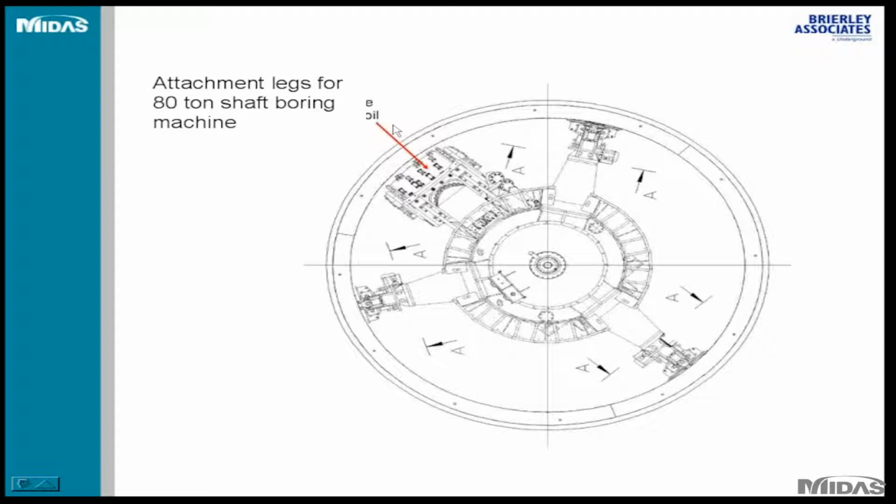You don't need them. So when the trim slab has hardened, you can just let it go and cut it at the very top, and eventually you remove all this system and start lowering your TBM down the shaft and start the breakthrough through the segments. Of course, there is a certain special design at the breakthrough in addition to the segments, because the segments themselves wouldn't be able to support the forces induced by the moment and shear from the cutting of the breakthrough by the TBM.